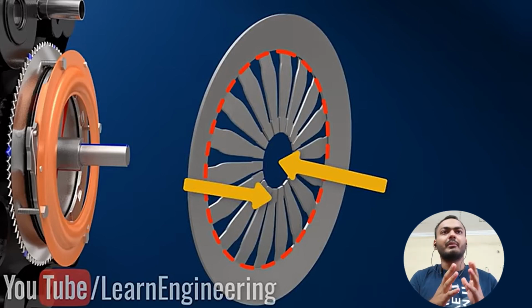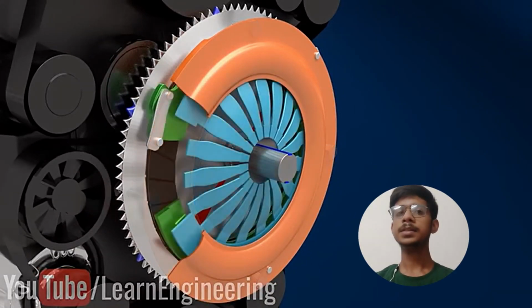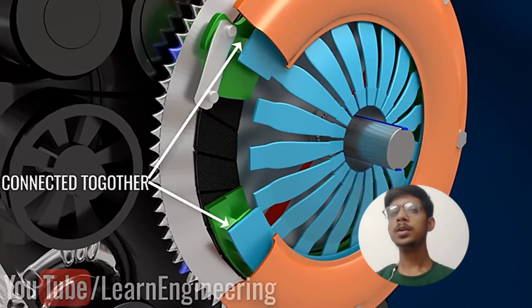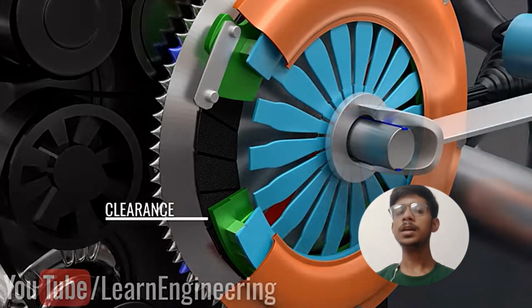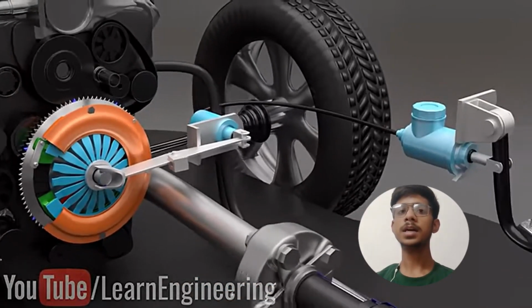Let's take a cross section of the assembly to understand this configuration better. The outer portion of the diaphragm spring is connected to the pressure disc. This means if you press the inner portion as shown, the pressure disc will move away from the friction disc, thus discontinuing the power transmission. A hydraulic system transfers the clutch motion to the center of the diaphragm spring. When the diaphragm spring is pressed, the power flow is discontinued, and during this time you can make a gear change. The clutch is released after the gear change and the power flow continues again. This is how the clutch works.